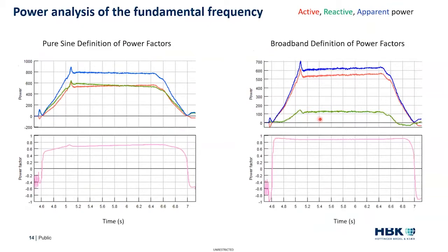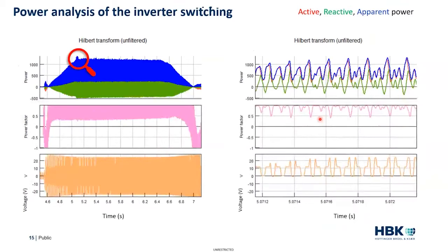And what's more, nCode uses a different approach. Rather than taking an average where we're limited to only getting the half rotational cycle frequency, within the nCode software, we can also use a method called the Hilbert method, where we can start to calculate active, reactive, and apparent power right at the very high frequencies, the switching frequencies in the inverter. So by understanding what the inverter's doing, we can start to hopefully improve the way that efficiency is building up through our vehicle to look at that.